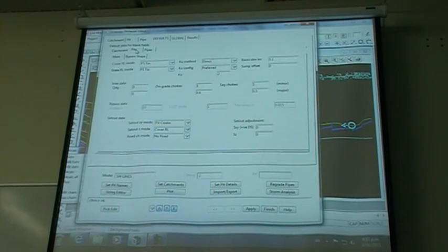Okay, again a lot of this is already filled out. We'll keep our KU factor, which is our head loss through the manhole, at 2, so it's nice and conservative. And we just want to make sure that our set out data has the set out XY mode as the pit centre, the set out Z mode is the cover RL, and the road change, we're ignoring the road data at the moment, okay?